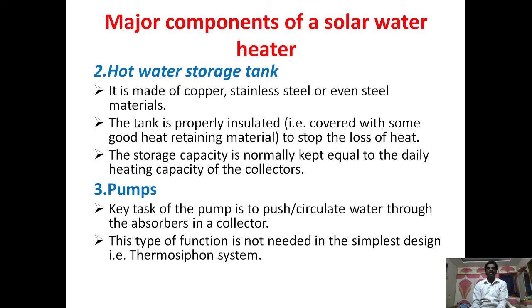Now see the third one, pumps. The major function or role of the pump is to circulate the water through the absorbers in a collector. From the tank to the collector, to circulate water through the absorbers, we need pumps. Generally, this type of function is not needed in the simplest designs such as the thermosiphon system.